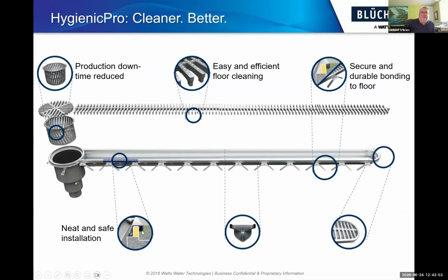So that's about a 10 millimeter wide by 11 millimeter surface that can be filled with a suitable caulking material or the flooring material, whether that's the epoxy or the urethane. And then when you get some expansion and contraction, some traffic going over that drain, that absorbs any of those forces and allows it to stay adhered and therefore sealed off.